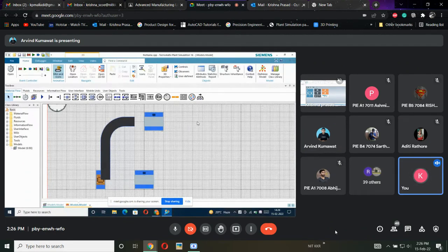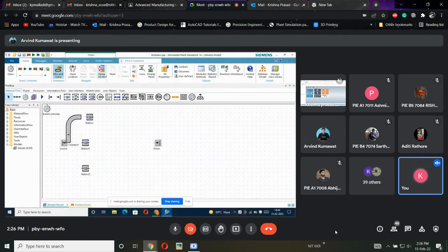Click on 2D, open 3D transformation. Now your model is 2D. Here you can create your complete model if you are familiar with 2D. Once you have done the modification in 2D, then again convert into 3D. This option will be enabled when you start your model in 2D only.